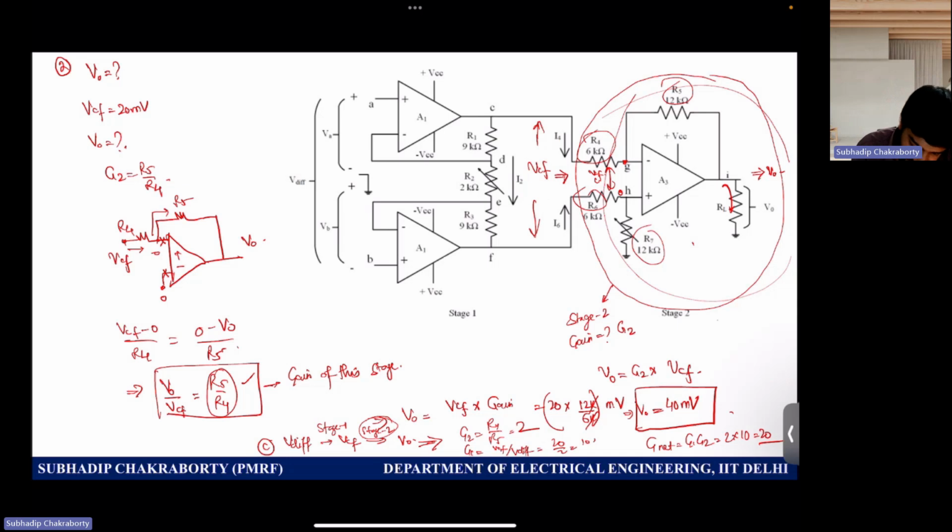And coming to the final part, the internal input impedance. You see from this side, since no currents can go through these ports, what we can infer, the internal impedance is infinite. So this is because input current is 0. So infinite, right? Infinite input impedance. So these are the 4 parts of how you solve this problem.